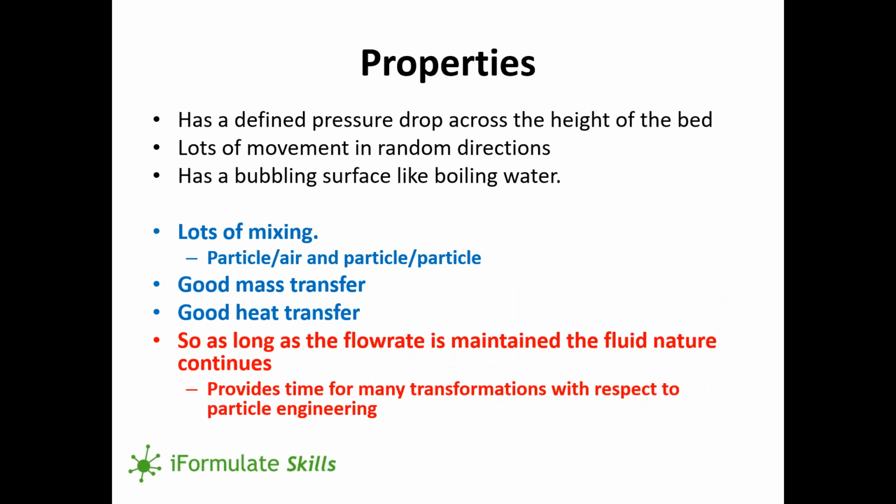The next slide talks about the properties of fluid beds. So there is a defined pressure drop across the height of the bed, and that's dependent upon how high the bed is and the nature of the particles that you've got in the bed, how heavy the particles are and what sort of shape and porosity.